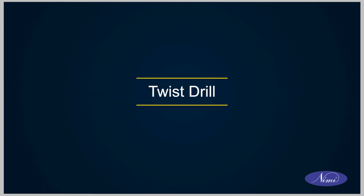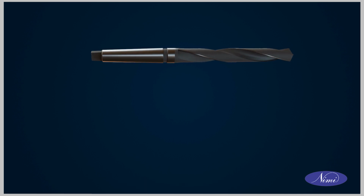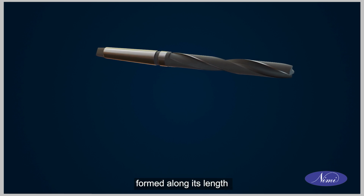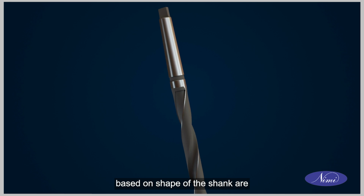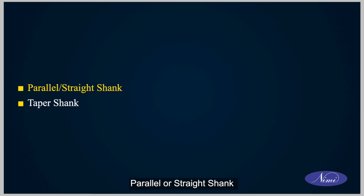Twist drill. Twist drill is the most commonly used type of drill bit. It has two or more spiral or helical flutes formed along its length. The two basic types of twist drills based on shape of the shank are parallel or straight shank and taper shank. Parallel shank twist drills are available below 13 mm size.